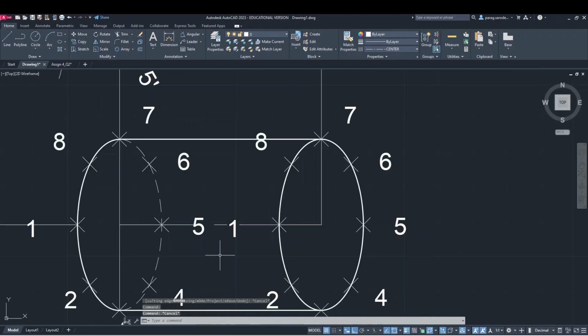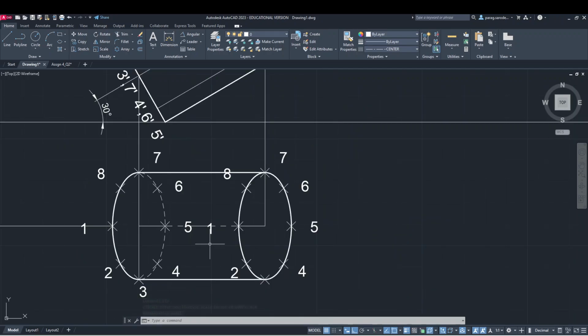Now if you want to change the scale, again we can use LTSCALE. So in this case 0.6 is there, so let us keep it as 0.4. Okay, so we see that this center line appears better now. So for greater visibility, let us move this one to here, close to this point. So let us move this one also to here.